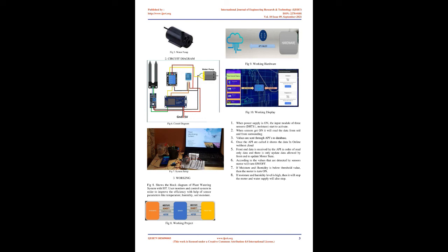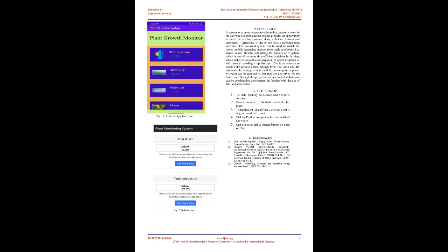ESP8266EX offers a complete and self-contained Wi-Fi networking solution. It can be used to host the application or offload Wi-Fi networking functions from another application processor. When ESP8266EX hosts the application, it boots up directly from an external flash. It has integrated cache to improve the performance of the system in such applications.